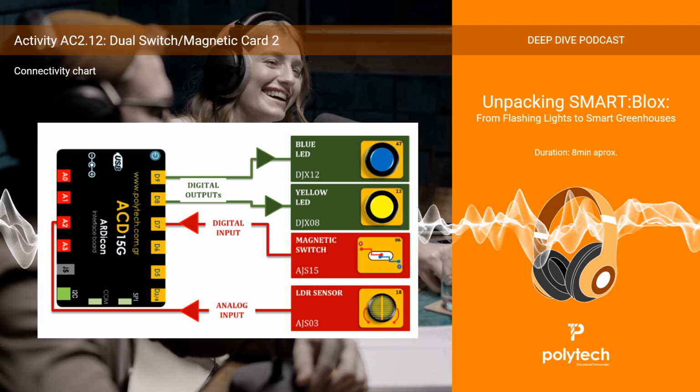It's nested again. First, the magnetic switch D7 detects a magnet. Then it checks the light sensor, A2. Okay. Inside that magnet present condition, if the LDR reading is less than 50, it's dark. Then turn both blue, D9, and yellow LEDs on. Like a security light and an indicator? Maybe. Then if the LDR is 101 or more, it's bright. Then turn only the blue LED on, yellow off.